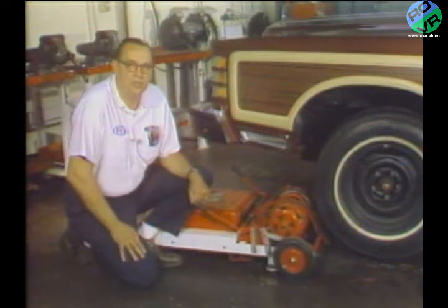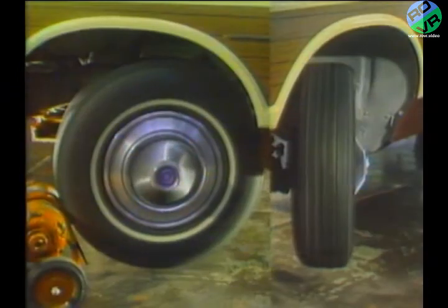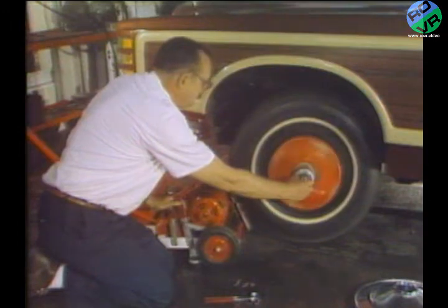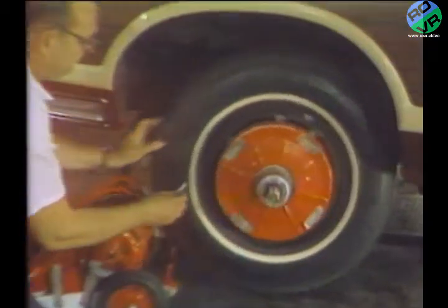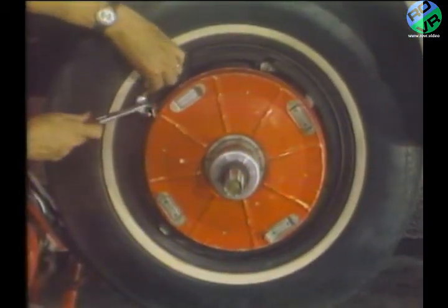You also know that good equipment is a must, especially when balancing steel-belted radial tires, which often require balancing to 1/4 ounce or less. Remember also that tires can be out of balance in 2 directions. This means, of course, that wheel assemblies can be out of balance up and down and side to side. Proper wheel balancing requires that the entire wheel assembly be balanced in both directions, and this means balancing for up and down and side to side.